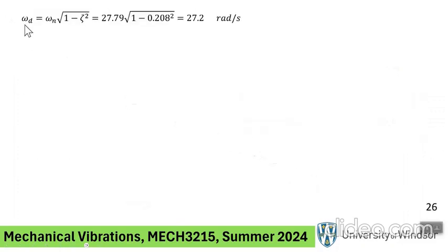So we go here, we need the damping frequency, because we are considering not only the steady state response, we also want to do the transient response. So that happens with omega d, that dies down with the frequency omega d. Okay, remember that we have transient plus steady state.